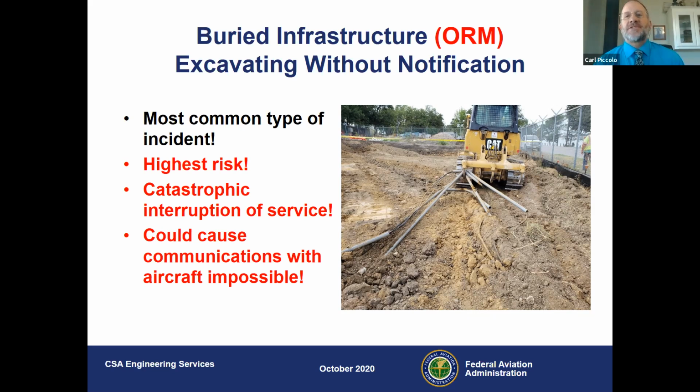We've had several instances where the cutting of cables underground has caused all the transmitters in that radio transmitter and receiver site to key. It basically renders communications at that airport useless. All of the radios will heterodyne with one another, and the controllers and the pilots can't talk to one another. We have films within the FAA of where we've lost communications at an airport.